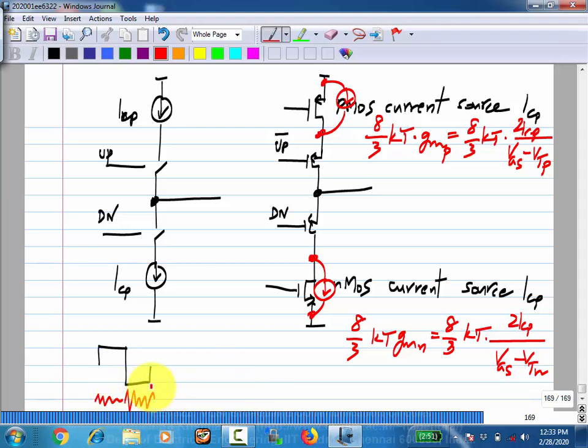Okay, but if the two have the same variance, I mean the same statistics, it will be like a single white noise process. Otherwise, if the spectral density here is different from the spectral density there, you have to take some kind of an average spectral density, because this is anyway getting low pass filtered by the transfer function, right? So if, let's say, this spectral density was 2 times this spectral density and each one is on for half the time, the effect will be the same as a single white noise source whose spectral density is 0.75 times that. Okay, it's the average of these two.